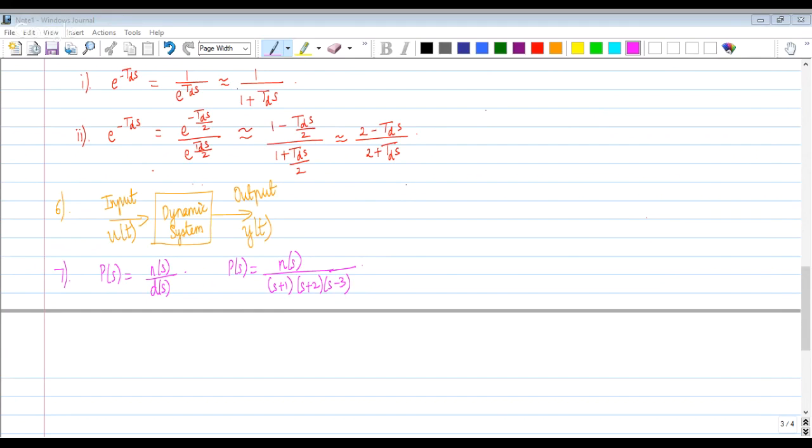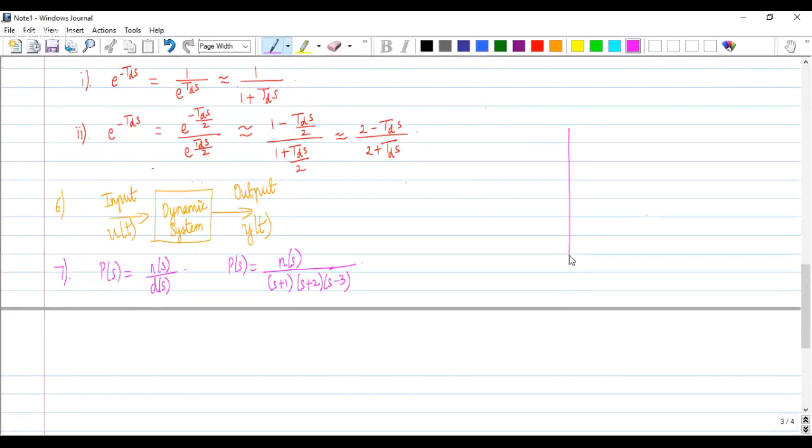Of course, the next question is, what is the problem that we face when poles are to the right of the imaginary axis? It's regarding stability, right? So let's say we have poles to the right of the imaginary axis in the S-plane, then it means that the system is unstable.